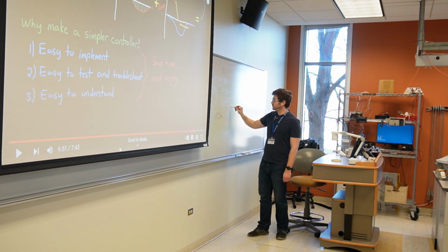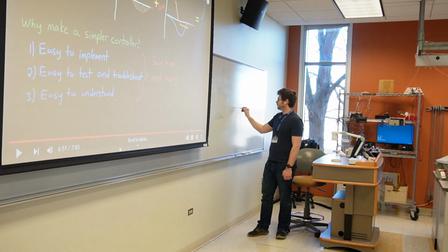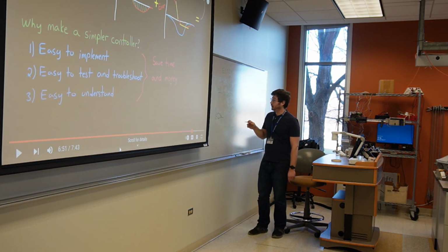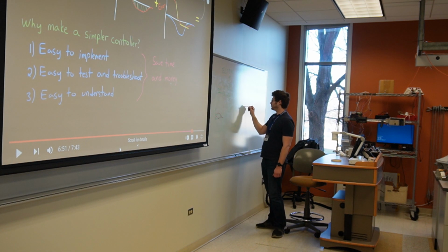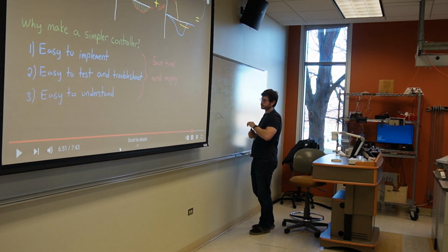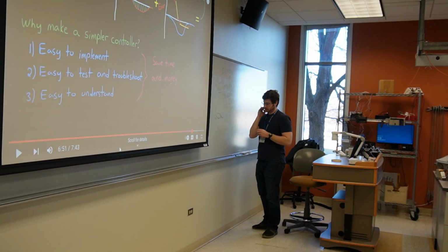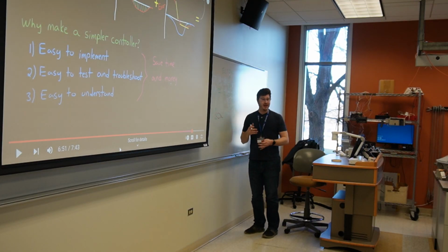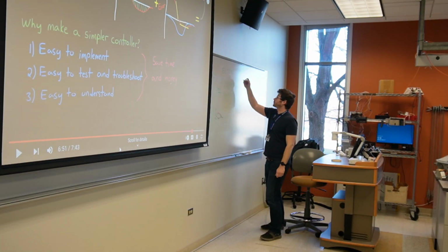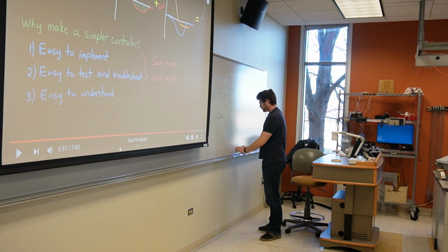And if you set it to 0, it removes that controller. So if you didn't want that creeping motion, that creeping error correction to be in there, you could set it to 0. If you wanted it to creep fast or slow, oh, I should go over this too. If your I is really high, if it's a little bit too aggressive, if it gets mad a little bit too fast, it'll oscillate.